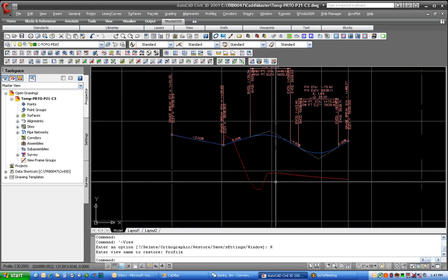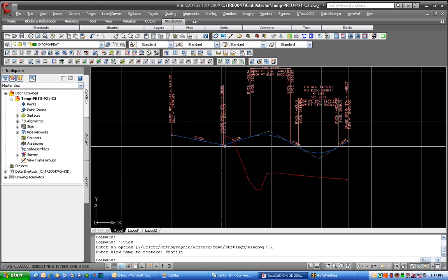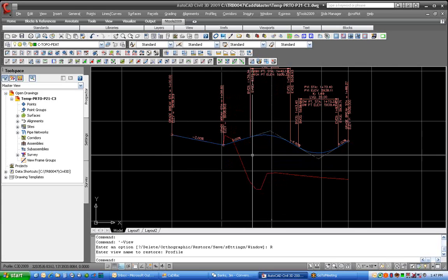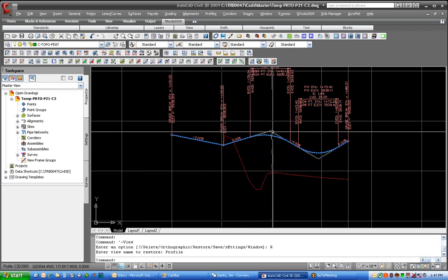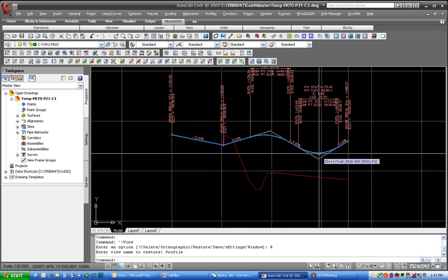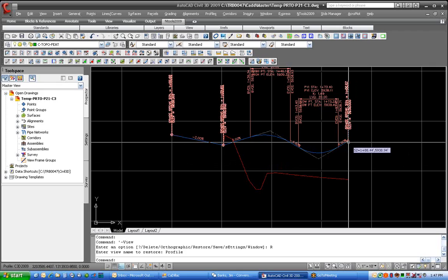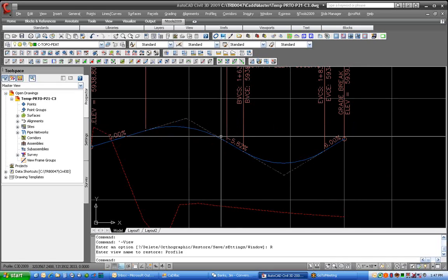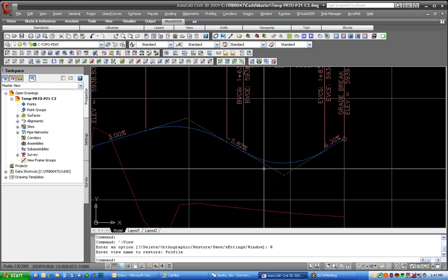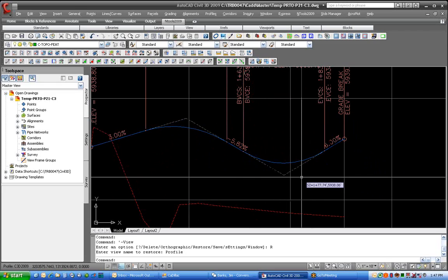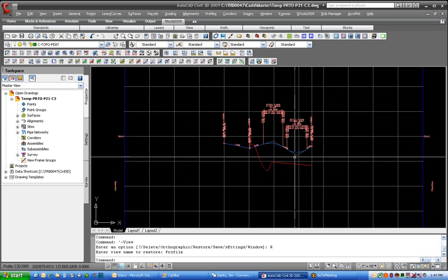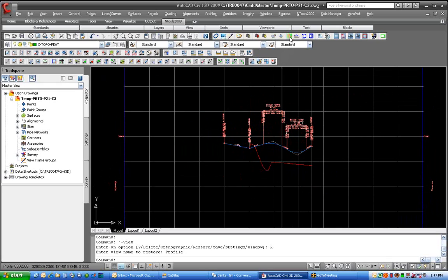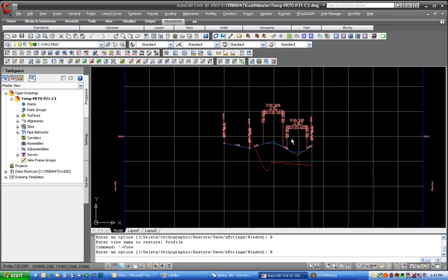So I also have a real basic profile coming off the street center line to flow line, and then we have a little high point so we can get our pipe in for our culvert, then a little low point where the fence line is, and then we come back up to the building pad. The grades are actually what they had in the original document, so we kind of left them that way, which is another reason we wanted to put in a profile, because that would have been quite a nasty grade break. We're looking at about 12% grade break at the bottom there, to try to get vehicles over. So we thought we'd do a little bit of grading with nice vertical curves in profile data.